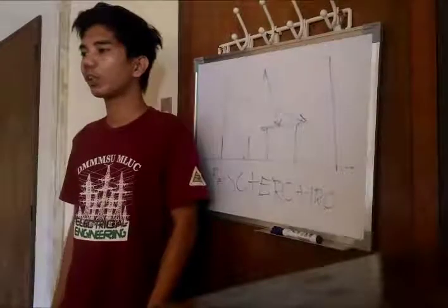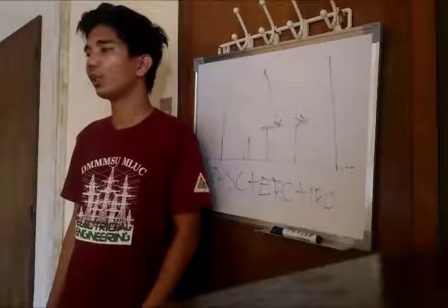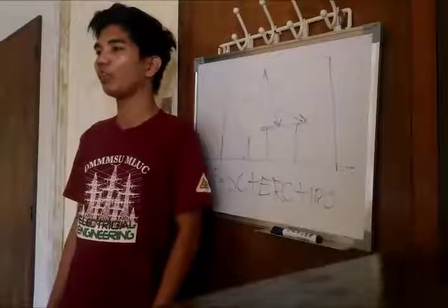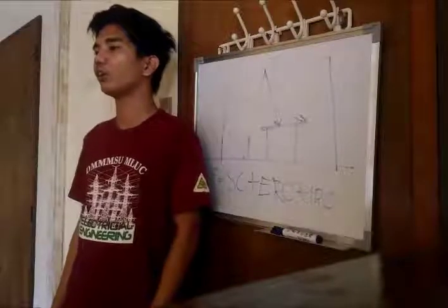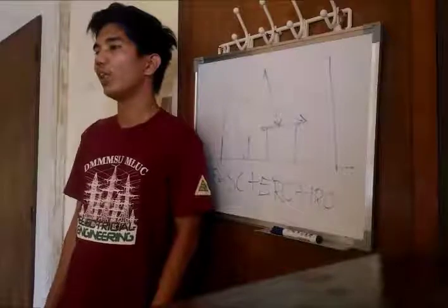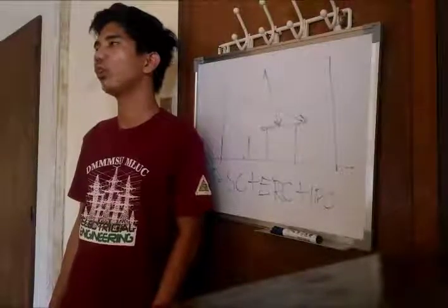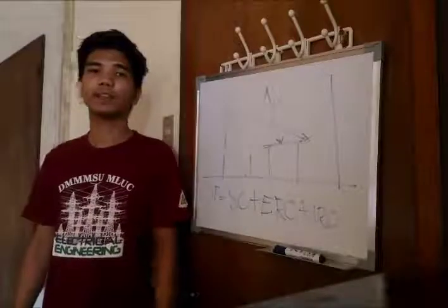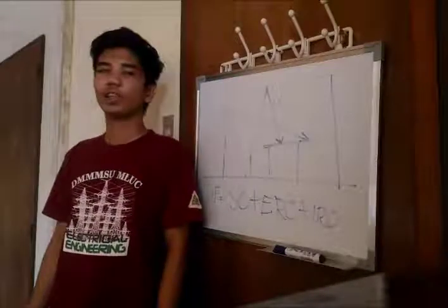Reflected light from the ground or other surfaces can also be caught by an overhang and directed back into the interior of a room. The result will be a slightly higher illuminance level and a more even distribution of light in the space. An example of exterior elements is the light shelves.